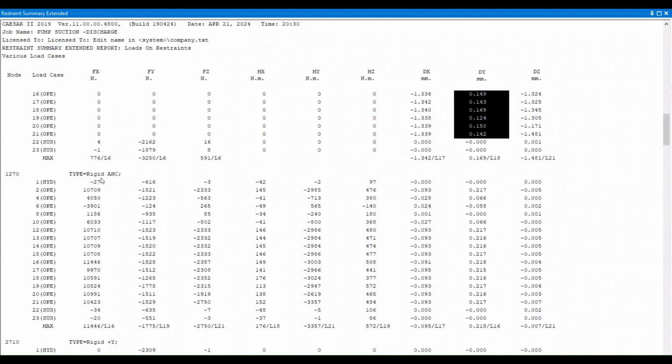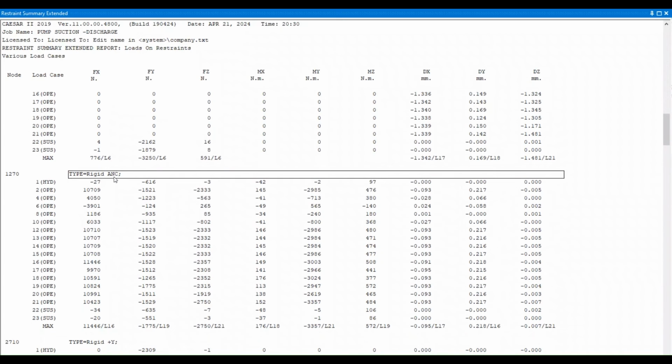And in the anchor, why are we considering an anchor? It will not be a real anchor. It is in order to get the moments. Wherever you provide an anchor, there only you will get the moments. That means the 6 degrees of freedom will be arrested, meaning displacements dx, dy, dz and rotations about x, y, z. If displacements and rotations are restrained, then only you will get Fx, Fy, Fz, Mx, My, Mz.